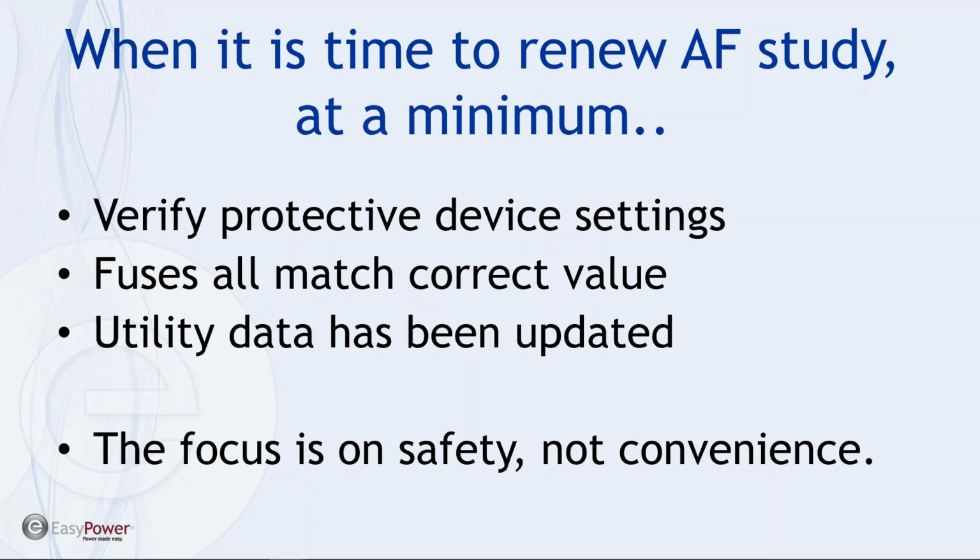And this includes elements that we don't think have the ability to change, which could be breakers, which could have been swapped out, and even molded case circuit breakers swapped out with different values, larger or smaller. It could be fuses that we unnecessarily or inadvertently changed manufacturers or fuse values on different phases. So we need to check to make sure the fuses match both manufacturers and part numbers and across the phases.